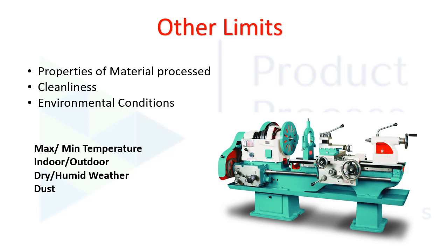Whether the machine will be installed indoor or outdoor matters, because when installed outdoor, it will be exposed to sunlight, rain, and dust. So whether the machine is capable of withstanding all these external things or not, and whether the machine is okay to be installed in a dry or humid condition. In the case of humidity, there will be some water vapor present in the atmosphere that may ingress into your compartment, particularly for the electronics component.